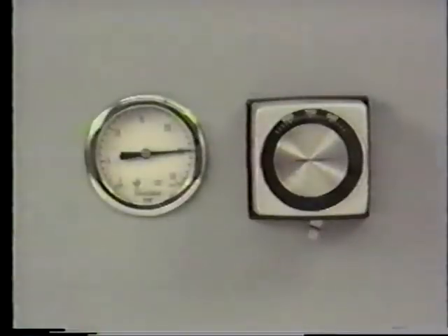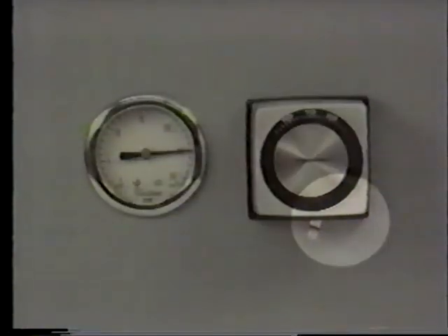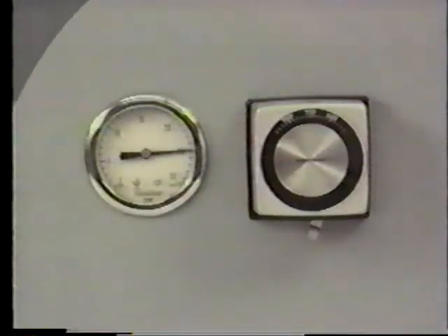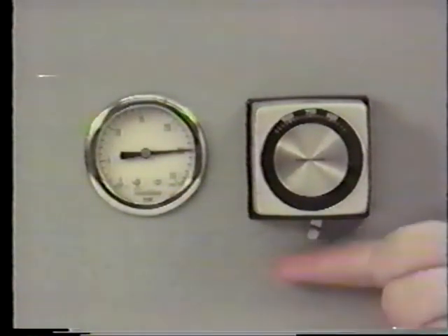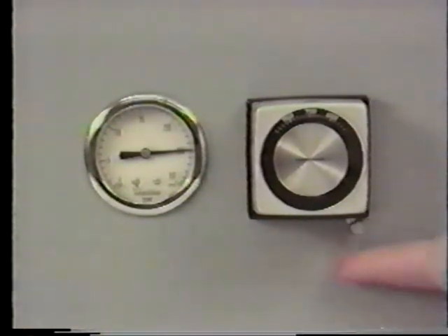Some models of day-night thermostats have a local indexing feature. This is a lever on the thermostat that allows an individual thermostat to be changed back to the day cycle temperature setting, while other thermostats in the system continue operating on the night cycle setting. This feature is especially useful in meeting rooms or classrooms that may be used at night.